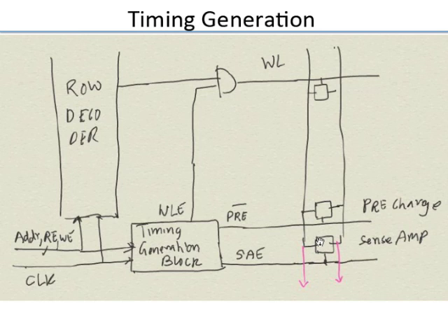And then you have the sense amp, which usually now is a clocked sense amplifier. You have two back-to-back connected inverters with a transistor at the ground which is turned on or off. That is the sense signal. These signals go like this, and in addition you might have a signal to disable the word line. So you have a basic timing generation block. The question is what is inside this block? What goes in? What are the considerations, etc.?